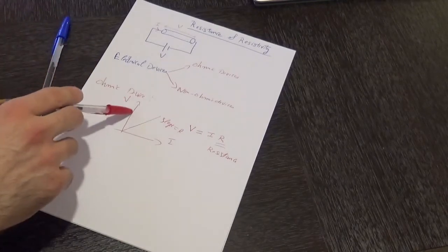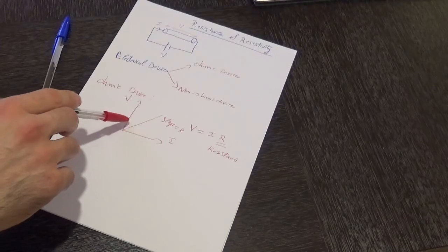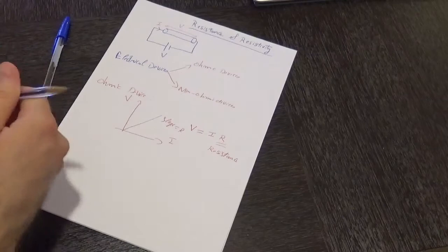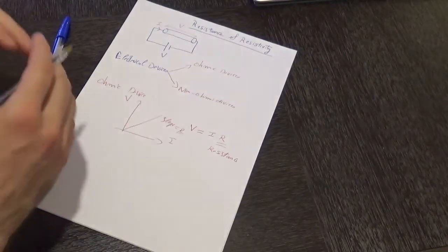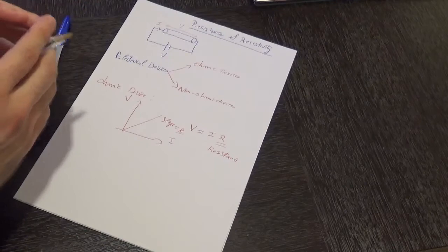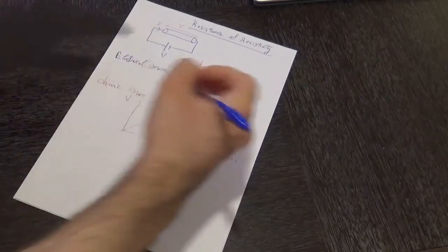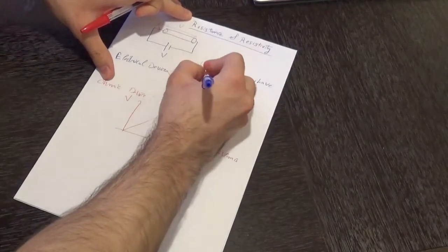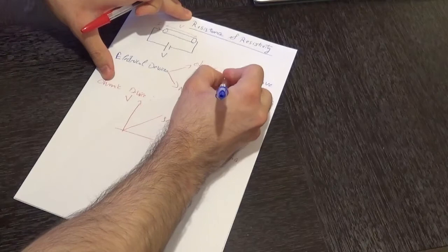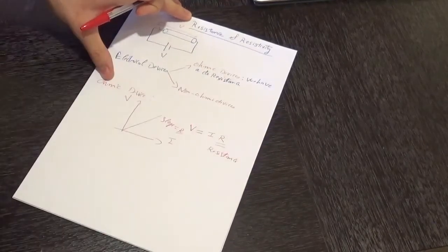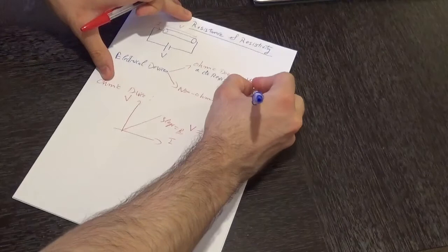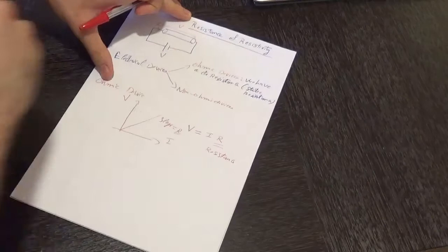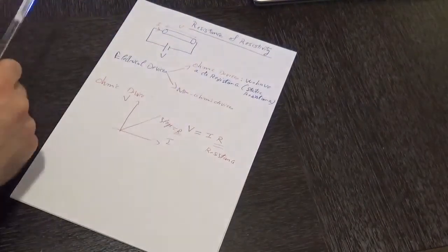That implies that the resistance for an ohmic device is also a constant. So it doesn't matter how many times you vary the voltage for an ohmic device, the electrical current is going to vary in a proportional manner in such a way to keep that value of R always a constant. So for an ohmic device, we always have a constant resistance, and we label that resistance as a static resistance. Now moving on to the case of the non-ohmic devices.